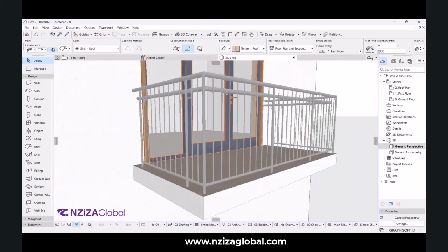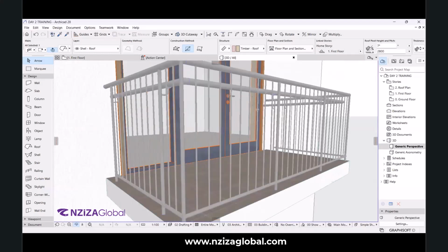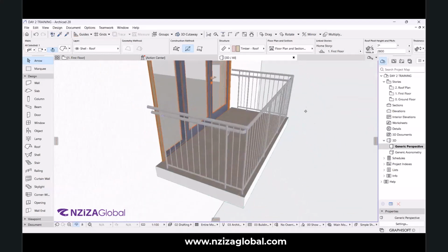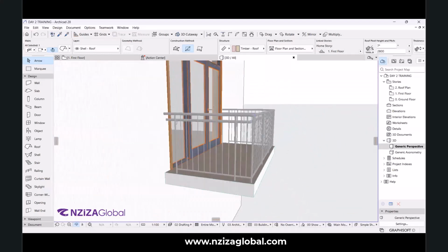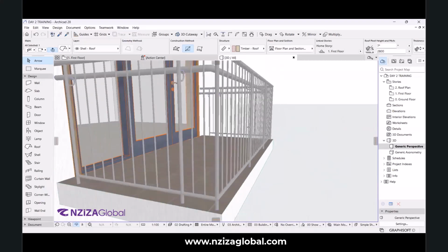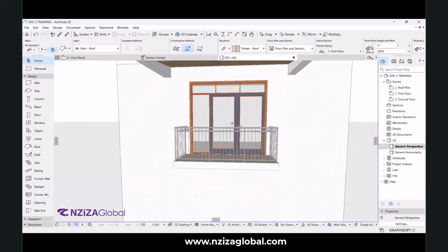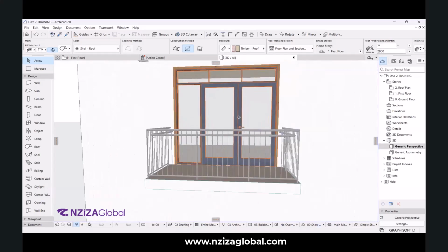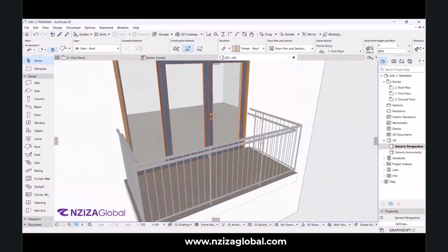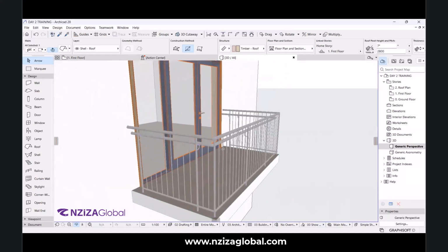You must understand that this rail must be vertical. I see a number of designers, but there is no architect who can do it. Designers or engineers put this vertical rail, balustrade, as horizontal this way. Architecturally, that is a mistake. So you must make sure they are vertical, okay?